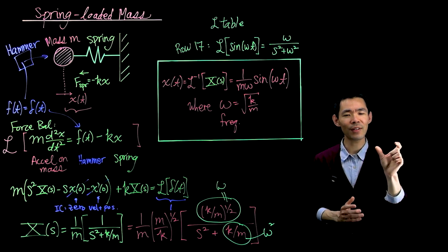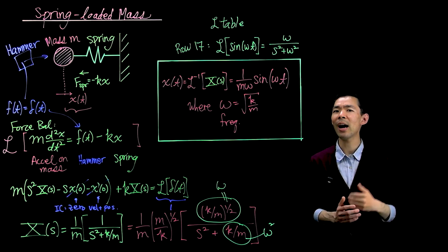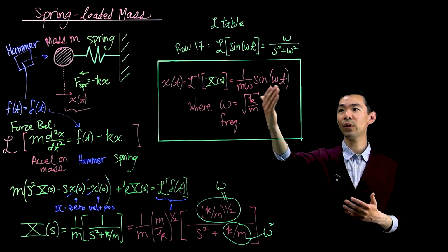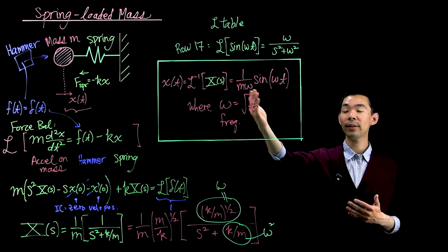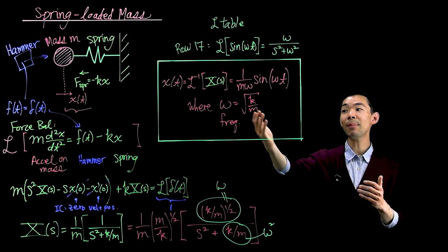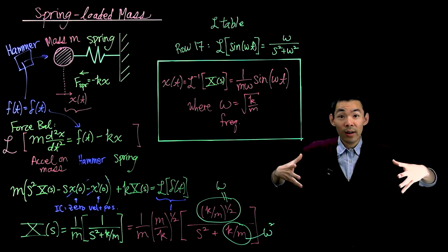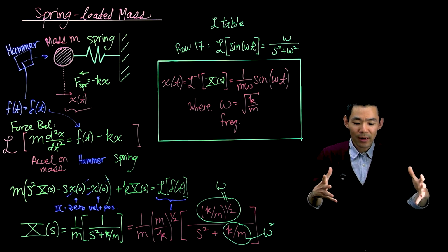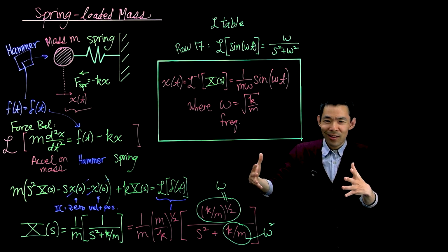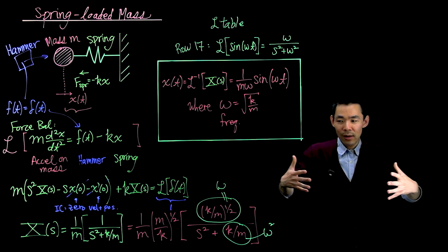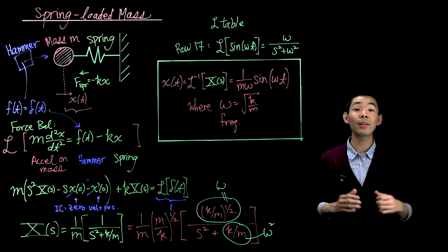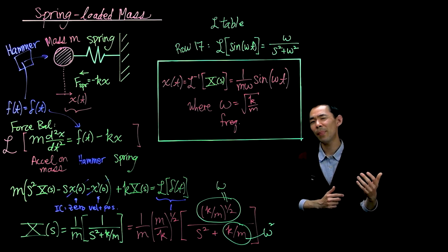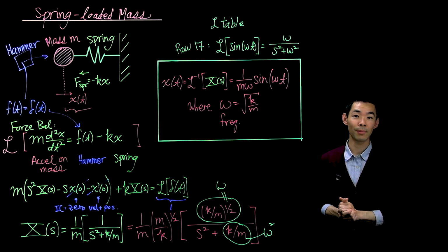If I have a stiff spring, I whack it, it's gonna have a very high frequency. So the sanity check of omega going up with the stiffness of the spring going up also makes sense. Same with the mass. If you make the mass very, very large, so that the ball is a massive object, you whack it, you'd kind of expect it to go slowly, right? Because it's such a massive object that it's just gonna go back and forth extremely slowly. Therefore, the frequency goes down. Again, sanity checks based on what you physically would expect from a system like this.